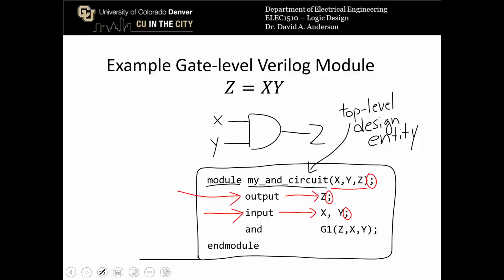And then we define an AND function, so AND of G1. So G1 is the gate instance, so that means that we are naming this gate G1. And every gate in your circuit needs its own identifying name. So we're just calling that G1 for gate 1.